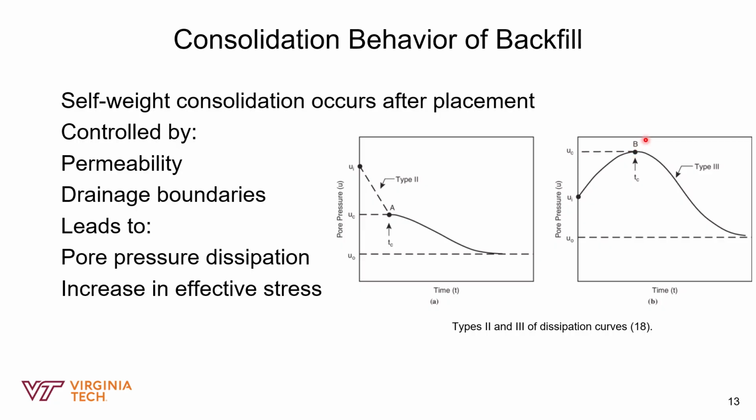And then it will start to drop. This can happen if we fill the stope too fast, and when I say fast, I mean faster than the water can escape. This is very critical because of the effective stress principle. Strength comes from the solid particles touching each other, so if the water pressure is high, it pushes the particles apart and makes the fill weak. We need that pressure to dissipate to achieve full strength.